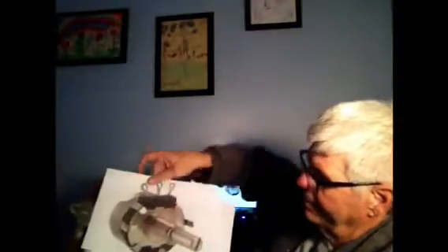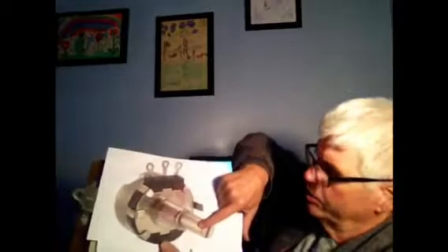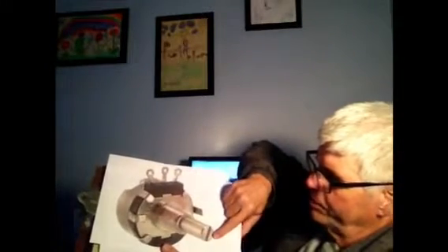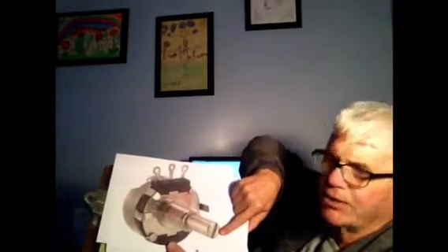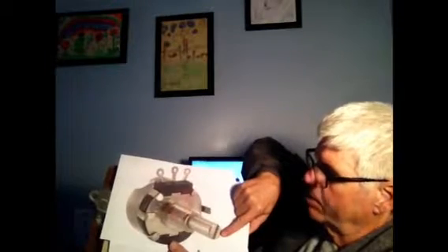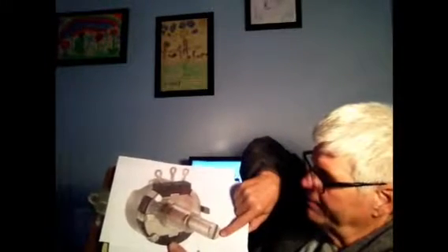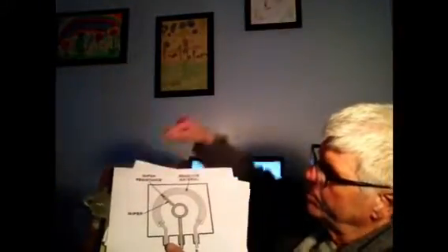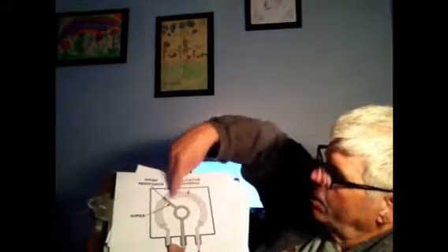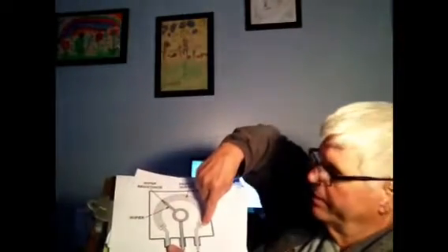This little arm moves when you turn the knob, when you turn the shaft right here, and your knob is just screwed to the shaft or glued to the shaft, or sometimes they're just pressed onto the shaft, and in a guitar it's usually just pressed onto the shaft. And when you turn that knob, you're turning that shaft, which is moving this little wiper along this big long resistor here.